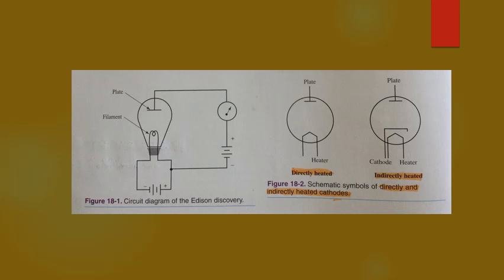Thermionic emitters. Better emitting materials have been developed in the years since Edison's carbon filament. Many materials, when heated to the point of emission, will melt. For many years, tungsten seemed to be the best material. It required a great deal of heat for proper emission, yet it was strong and durable. Tungsten is still used in large high-power vacuum tubes.